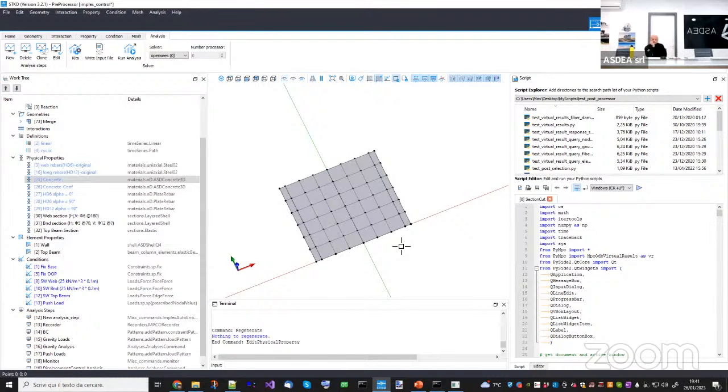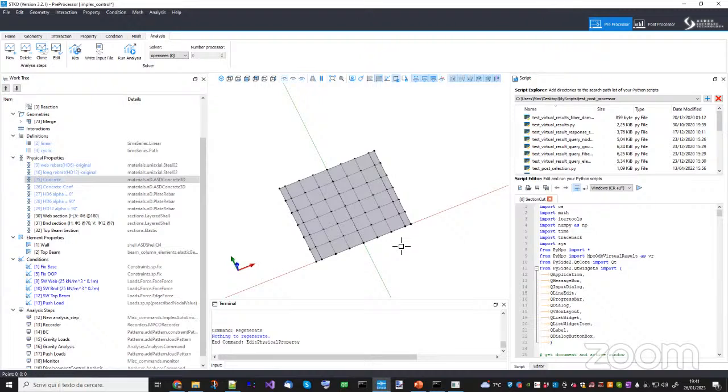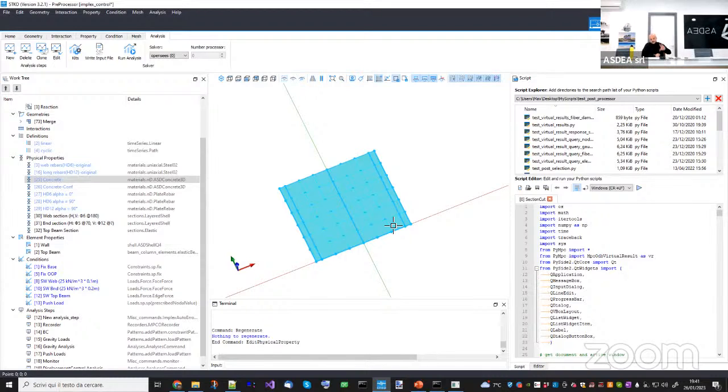I think one of the main reasons for the beam truss model is that they communicate the strain between truss elements that are perpendicular, right? So if you have a truss element that is in tension with cracks, it communicates to the truss element that is perpendicular to it to weaken the compressive strength of that element. And here you go back in the perpendicular direction to the full initial compressive strength, right? Or can you change that? Two different things. Now I understood what you're saying. Those are two different things.